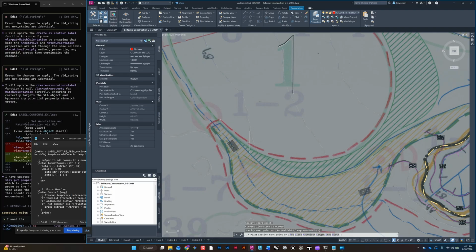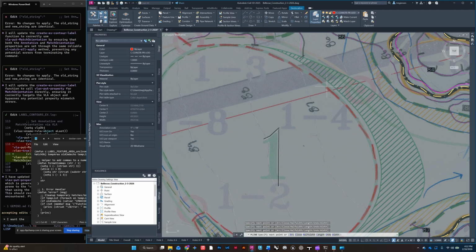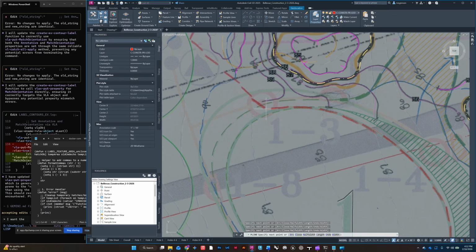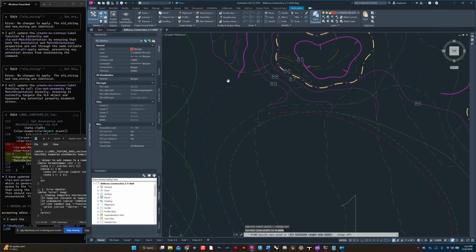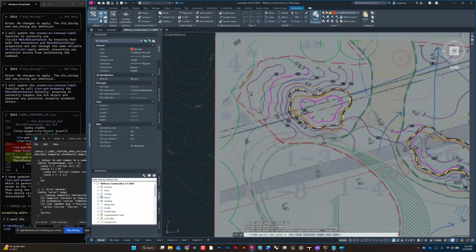So I always start it here and draw the curved line first, until you get to the point where it's turning straight again, and spline it now. And then use your snaps. Snap it to the endpoint, turn your snaps off, and then come up here.